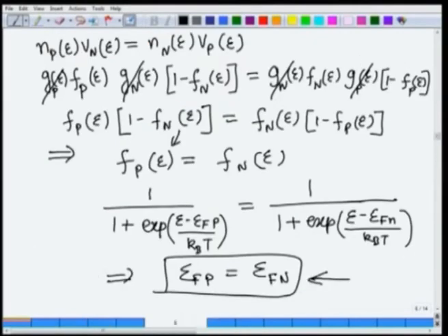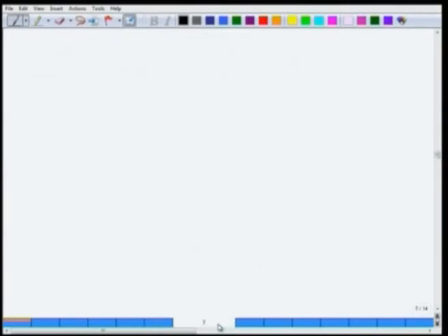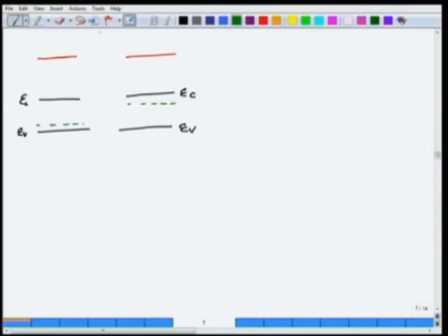Since we require this, let us see how we can make the band diagram. So, let us again do this. What are we going to do? Let us draw those band diagrams from number 6 again, where we had said that here is the vacuum level, here is the vacuum level, and here is EC and EV of one material, EC, EV of the other material, and they are the same since they are silicon. Only one has a Fermi level here, the other has a Fermi level here, and we have not joined them. We intend to join them right here.